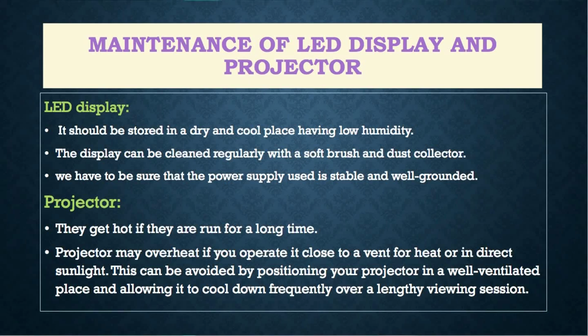But one needs to take special care while maintaining a projector because it is very sophisticated. So let us discuss how to maintain a projector. First, cooling the device. The correct operation of many electronic devices, including a projector, is harmed by overheating. While more modern and energy efficient LED lamps do not generate as much heat as their less efficient predecessors, they can still get hot if you run the projector for a long time.